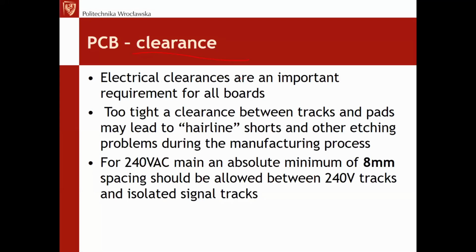Important thing that also has to be at some point considered is the clearance. What is a clearance actually? Clearance is the distance between tracks. If we get back to our first slide today, there was this parameter TT, the track to track distance. That's the clearance. The clearance is between tracks, or between tracks and pads, or between pads.